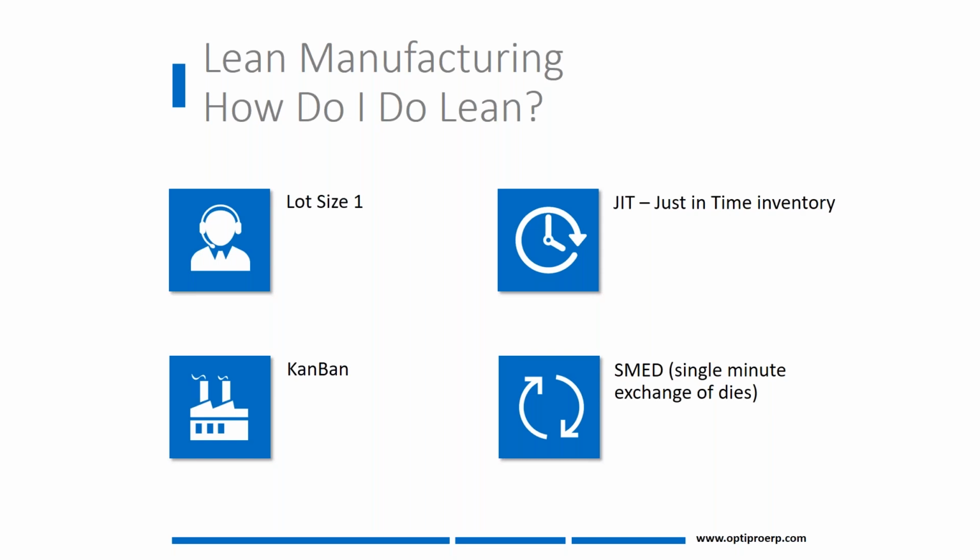Just in time. The concept of JIT has been around for a long time. And again, this is very supportive of lean. Just in time says, let's deliver things when we need it, in the quantity that we need it, at the place that we need it, just in time. Listen to the words, right? We're talking about lean manufacturing. We're driving out queue time, and getting things where they got to go exactly when we need them, right? If I don't need it, I shouldn't have it.